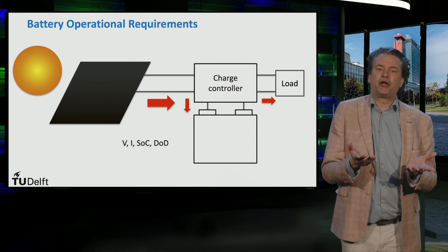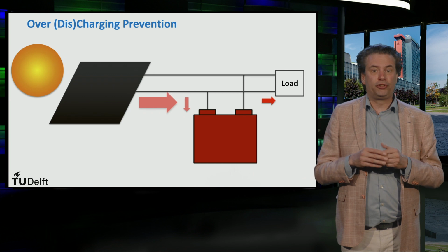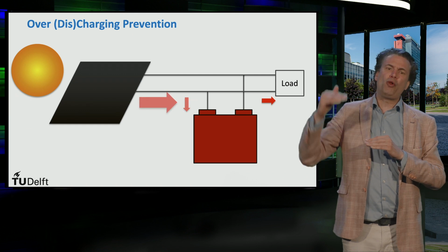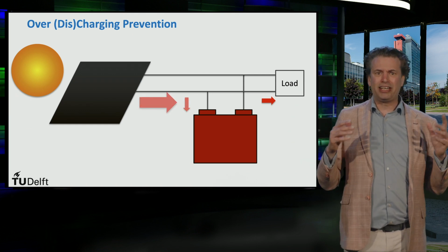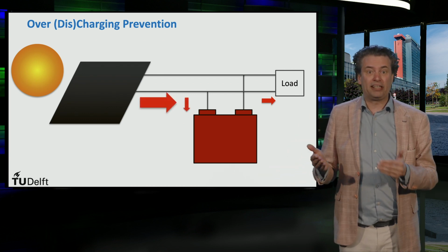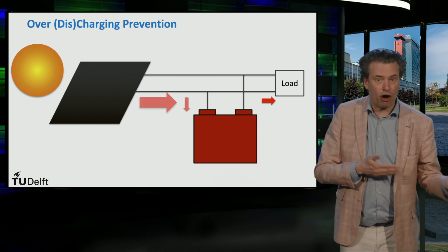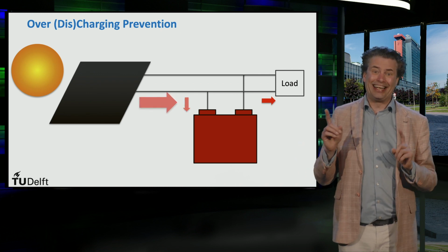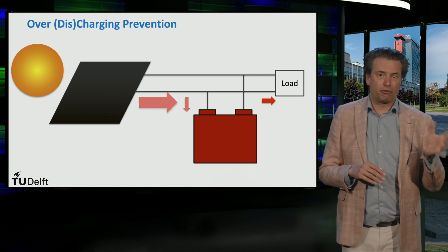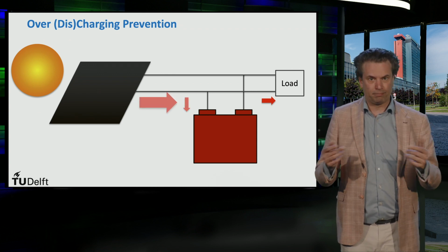Suppose in the same scenario when the sun intensity is very high, the battery will get charged very fast due to the PV module producing higher currents. When this battery reaches its full capacity, the PV module will still continue to produce current feeding them to the battery. At this point, the battery will begin to get charged beyond its capacity. This is called overcharging of the battery. Overcharging the battery has a negative effect on its performance. It leads to several problems like gas formation, capacity loss, or overheating, thereby reducing the battery's lifetime.